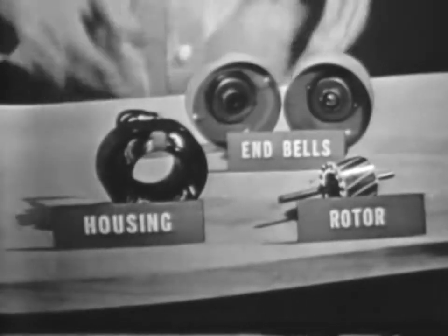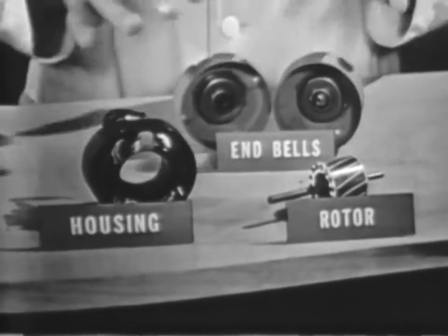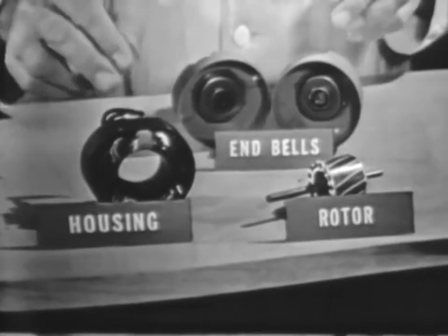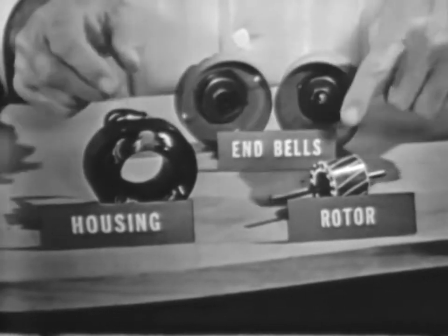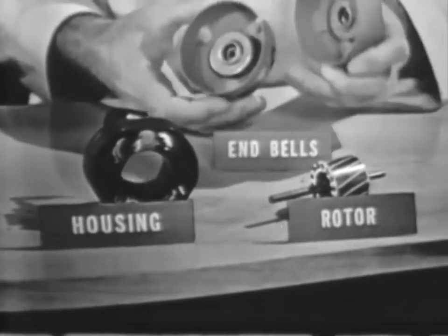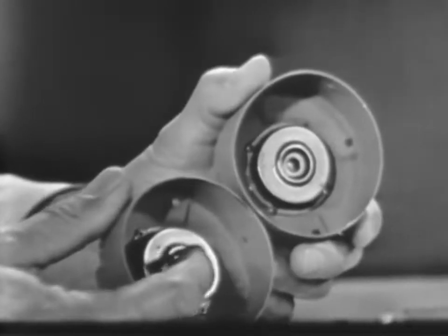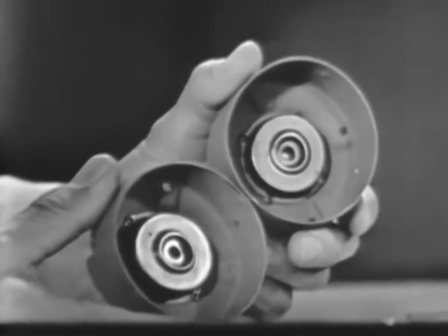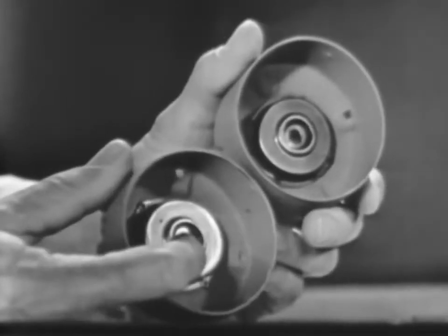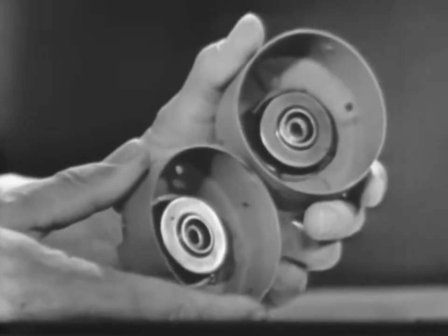This is a typical induction motor disassembled. Now, as we've said, it's very, very simple. We have the 2 end bells, the stator field windings, and the rotor. Now, let's take a look at these end bells. The end bells are used to house the bearings or the mounting devices that hold the rotor shaft in place. Now, notice there are no brushes or complicated brush holding devices at all. Just simply hold the bearings.